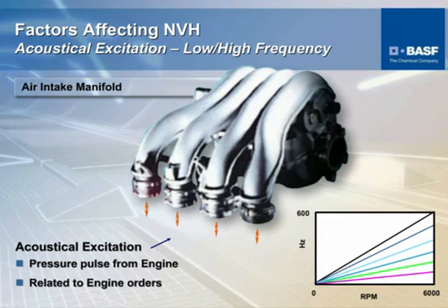The acoustical excitation can also happen due to the pulsation of the air that's inside an air intake manifold, for example. It is the pressure impulse from the engine, from the combustion that's going on and the firing and so forth, and it is related to the actual engine speeds.